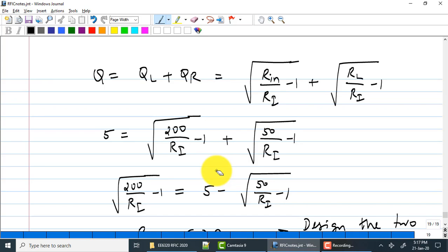If Ri gets to be like an ohm, okay, or a couple of ohms, just a wire connecting to an inductor and a capacitor can easily have several hundreds of milliohms if you are not careful. Okay. So you may find that at that point you hit the limits of what you can reliably design. Okay, which means that there is a limit on the upper quality factor.